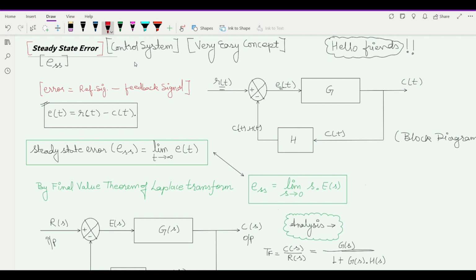As you all know, if the actual output of a control system during the steady state deviates from the reference input, that is the desired output, the system is said to possess a steady state error. These errors arise from the nature of inputs, the type of the system, and the non-linearity of the system components, such as static friction, backlash, etc. Aging or deterioration are also factors which cause error.